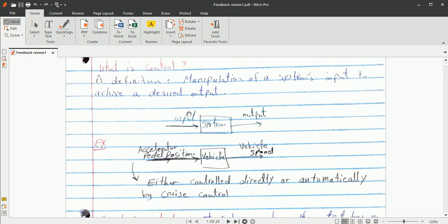But if you want an automatic control system, you want the system to automatically achieve a desired set point, your desired level. So for that system you need a feedback. You need a sensor to monitor your desired variable to compare with a set point. So from that comparison, a signal is generated, which is known as the error signal, which then goes to the controller. And you can design a controller to be an on-off controller, proportional controller, integral, PI or PID controller.